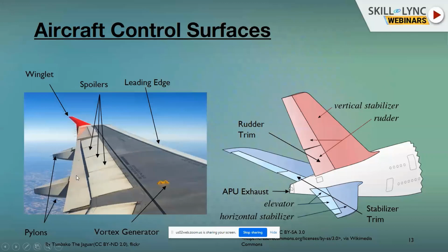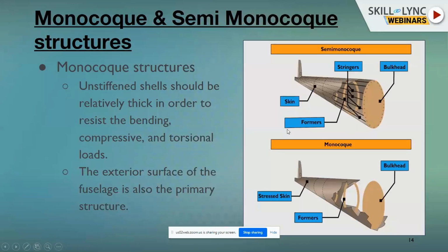Then your leading edge, and we call this the trailing edge. This is a winglet, which provides additional efficiency. It's good to have. It's not necessary. Few aircraft won't have a winglet at all in the future, but this is even a structural member, because it is only there to increase efficiency: it reduces the drag and increases the lift. This is the tail cone, your vertical stabilizers, horizontal stabilizers. This is the actual picture of how it behaves.